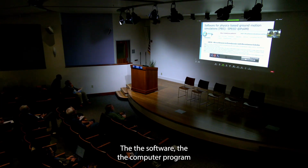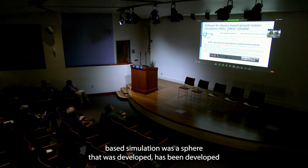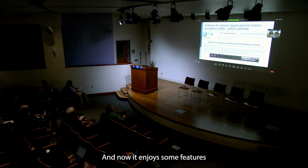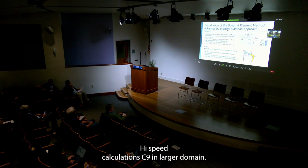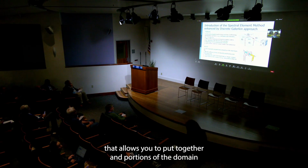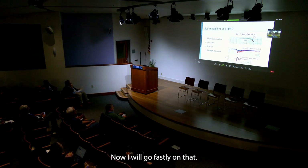The software, the computer program that we used for the elastic wave propagation problem, physics-based simulation, was SPEED, that has been developed for more than 20 years at Politecnico di Milano. Now it enjoys some features that allow you to perform in an effective way high speed calculations in large domains by taking also advantage of discrete Galerkin approach that allows you to put together portions of the domain with a different element size, with a different polynomial order. Now I will go fast on that.